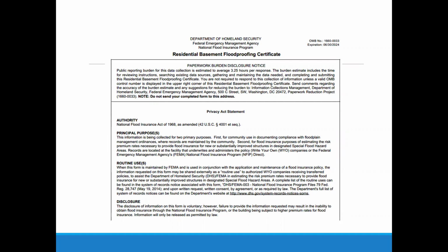So yeah, a dry floodproof basement for a non-residential structure does not have to adhere to the same elevation rules as the residential basement. So it was just built completely wrong, and so hopefully you can avoid a situation like that. That did not go well, but basically in that situation, they would have to fill in that basement.